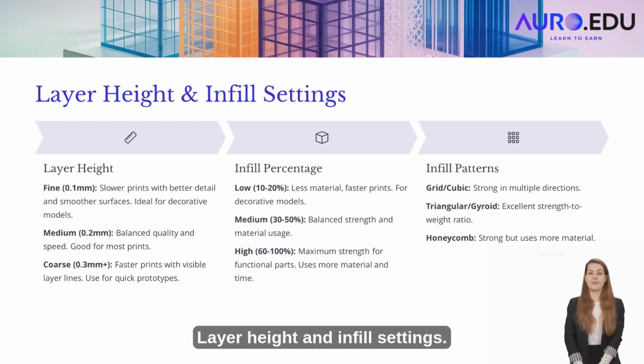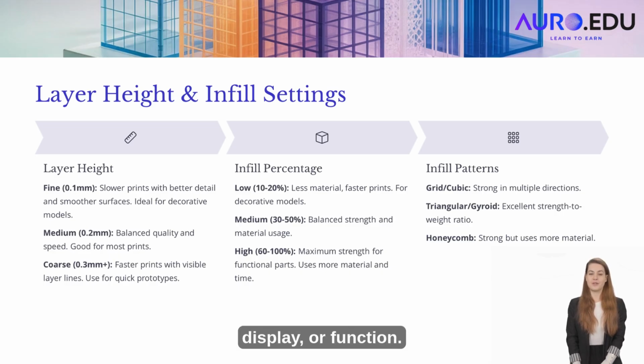9. Layer height and infill settings. Layer height determines resolution. Smaller layers yield smoother results, but take more time. Infill controls internal structure. Higher infill means stronger parts, but more material use. Choose based on the part's purpose, display, or function.